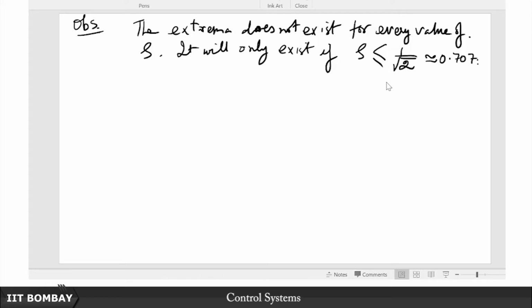Similarly, if you just show this frequency response plot to a reasonably, not a very absolute lay person, someone who understands frequency response but doesn't know about all the nitty-gritties, that person might say, okay, this is the kind of peak or trough that happens at this frequency, which I am not particularly fond of. So I want this to be restricted within this band. You see, immediately that also translates to a constraint on zeta, right? So we have a grip over this performance even in the frequency domain, which translates to some restrictions on zeta, okay.